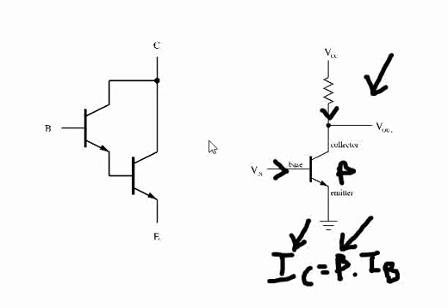In such cases, we use this kind of circuit which is called a Darlington pair. You can see here there is an NPN transistor with a base input, and the collector is tied to the voltage supply. The emitter output is connected to the base of the next transistor, and the output of the second transistor can be used to connect to your load.